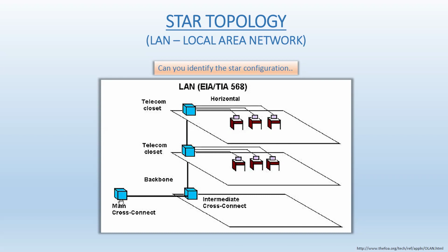What is this? This main cross connect is a room within a building where everything comes in from outside. All the phone lines, all the fiber lines, whatever communication is being brought in, it's brought into that room. Sometimes it is called the electrical room, which is kind of an iffy name, but a lot of people refer to it as such. The other name for that would be a demarcation point. Demarcation basically means point of entry. Sometimes it's also referred to as the demarc.